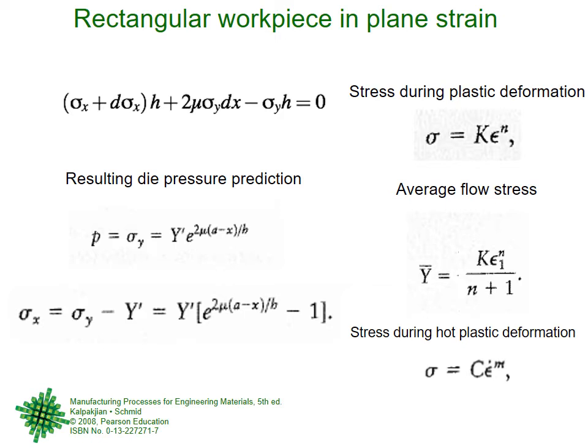So those of you who have already seen it, the others I always ask you not to look at the rest of the page, but this is the equation. Sigma is the stress, epsilon is the strain, and K and n are two constants of the material. n is called the hardening exponent, a small n, and K is the coefficient.